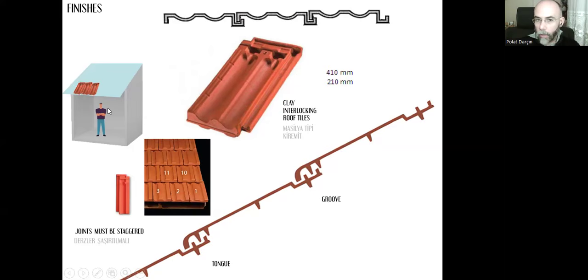Okay, we are laying these tiles next to each other. We create the first line, but how can we prevent them from sliding down themselves and being broken like that? We can use lats, timber lats, çıta, ahşap çıta. And first we can nail these lats over the water insulation or heat insulation, depending on our choices.